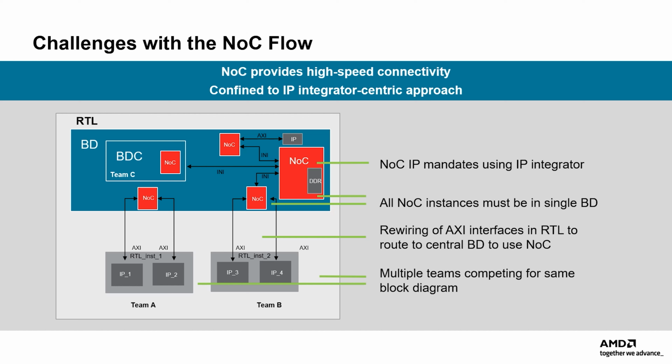The process of integrating numerous signals crossing the DFX boundary can be quite complex and can lead to QOR challenges in future RMs, since the AXI pin locations on the RM boundary are not allowed to change.